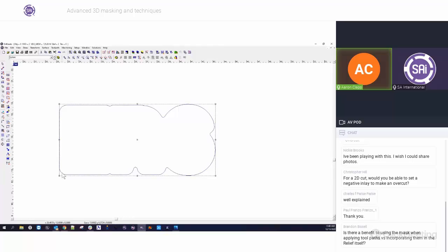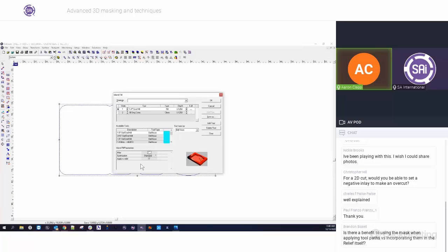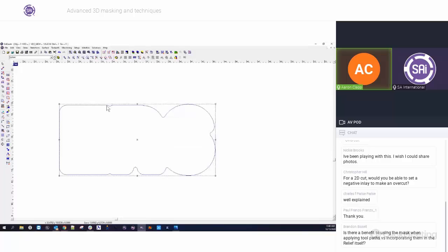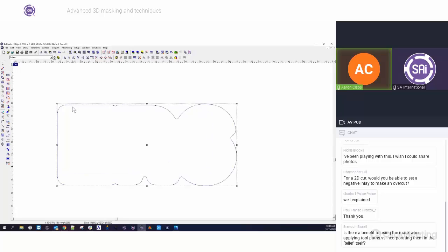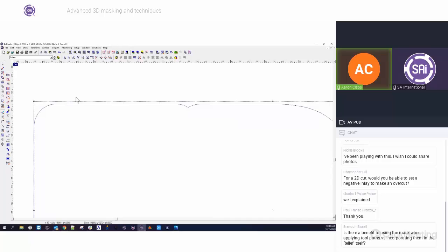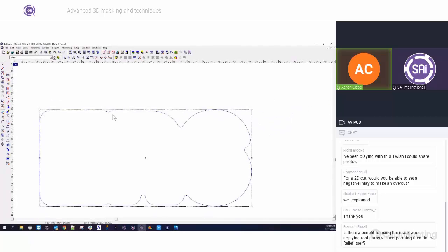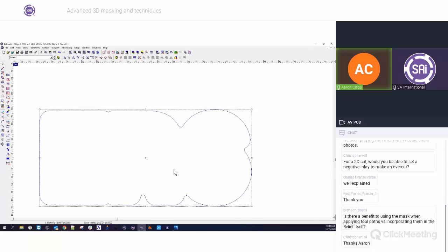If you do an inlay with the inlay feature, so if I were to do an island fill with the inlay option, the inlay option is mainly geared towards channel letters, and so what it does is it rounds off corners. It doesn't actually push the tool out beyond the edge of the path. And so that's where there's a little bit of a difference there. So maybe not, I mean, there's a possibility you could, but the easiest way I found to do it was just to take that shape and then just add an outline to it of however much I wanted it to overlap the previous cut.